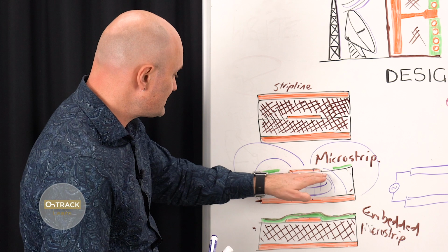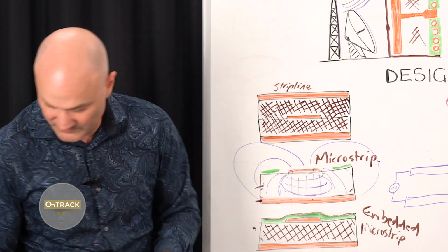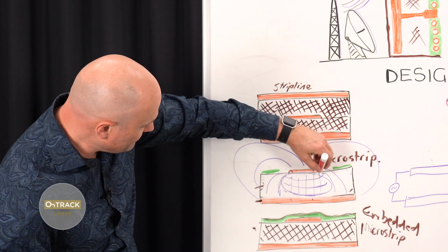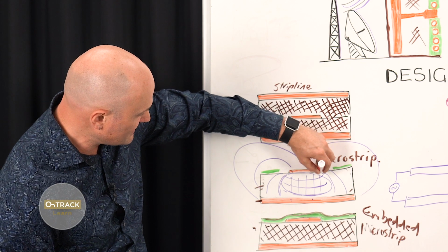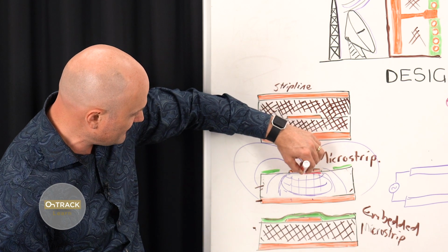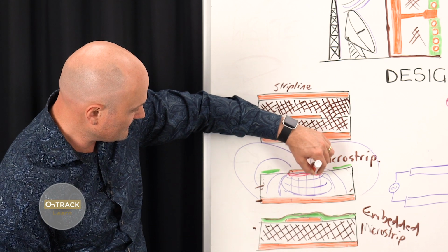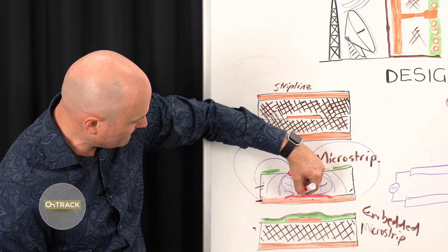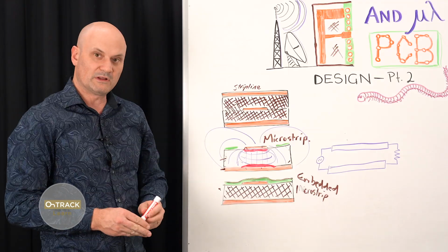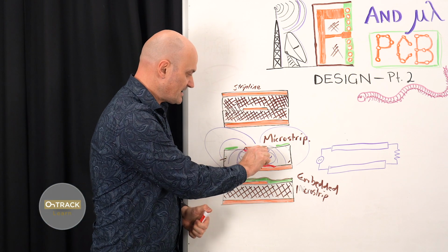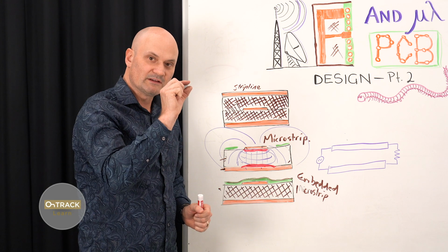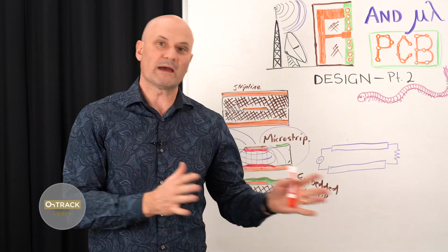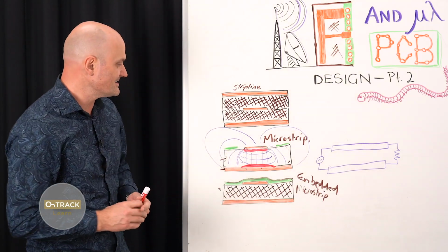And because this is the area where the coupling is, most of the RF and high frequency currents are traveling in the skin effect in this region right here. And the return path currents likewise are mostly traveling in this region of the plane. And because of that, it's actually the bottom surface, a very tiny area of the bottom surface of the conductor that's actually got the electrons moving back and forth at high frequency AC.